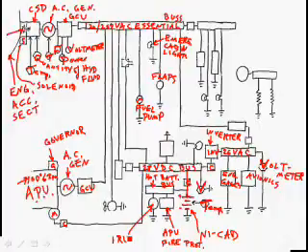So if for some reason you decided you needed to disconnect this contactor to turn the bus bar off, the battery would still be able to power the inertial reference units, and they wouldn't spin down, and then you'd be stuck without them for the rest of the flight. So that's very common. I think on the 777 they call it the ADIRU, Air Data Inertial Reference Unit. But regardless, the inertial navigation systems, sometimes they're called INSs, inertial navigation systems. So those would be common things to be on a hot battery bus.